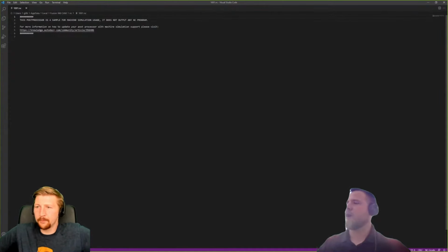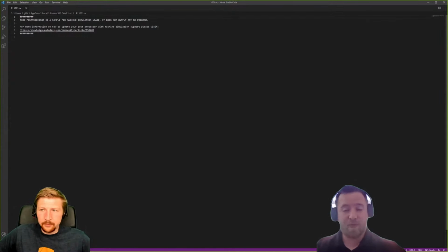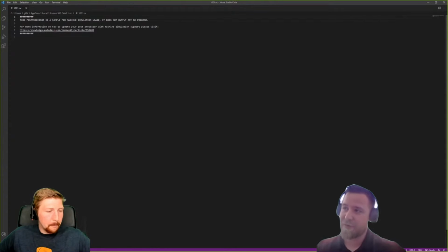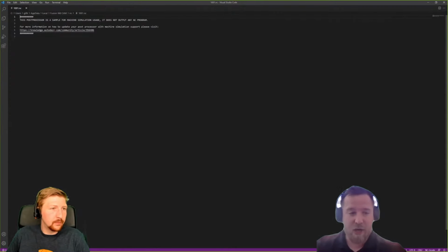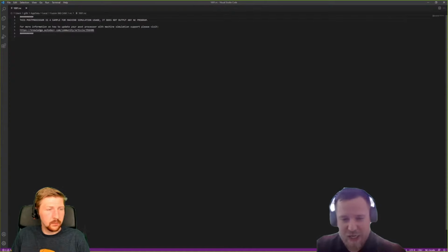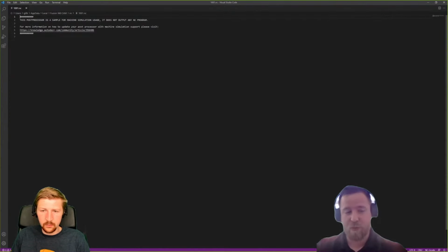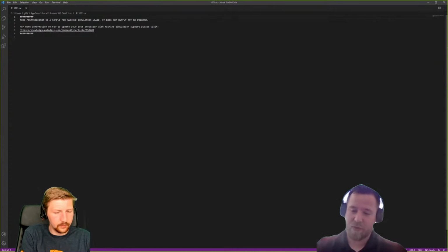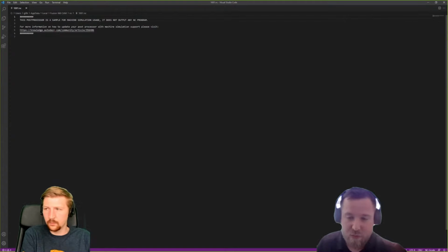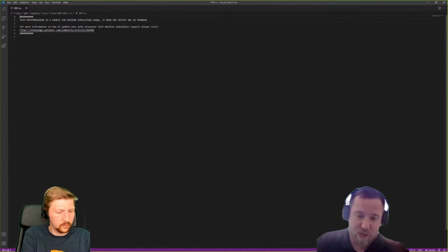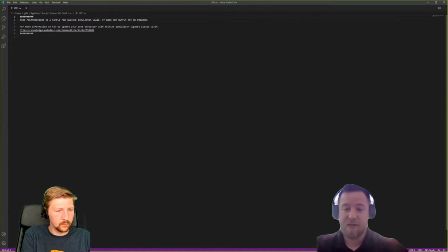Cool. Right. So we've posted out using that machine simulation post. Interestingly, it's given me no NC code. This is really important because as a public preview, we do not want people to use this machine simulation post as output code to run on the machine, purely because the machine kinematics will change the output. For example, if they've been using the Haas post they've been using for the last 4 years, and then they transition to a post which has machine simulation and special kinematics defined inside of Fusion 360, their outputs will be very different.